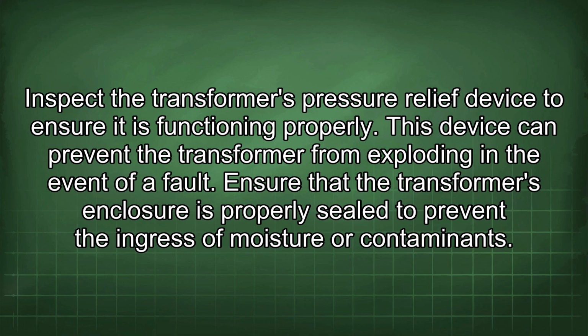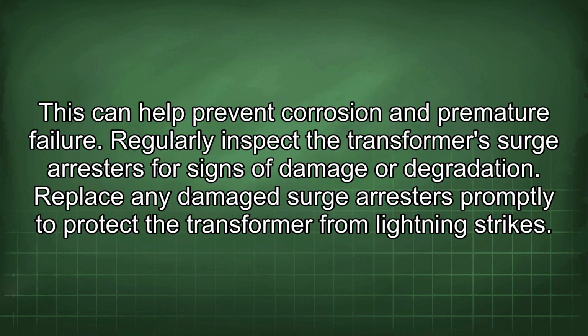Ensure that the transformer's enclosure is properly sealed to prevent the ingress of moisture or contaminants. This can help prevent corrosion and premature failure. Regularly inspect the transformer's surge arresters for signs of damage or degradation. Replace any damaged surge arresters promptly to protect the transformer from lightning strikes.